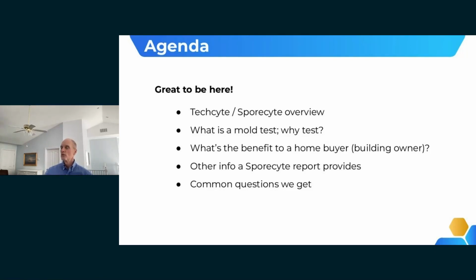You might look at it and ask, is there a moisture issue causing that? Is it a water leak, a roof leak, a window leak, or high humidity? If you could feel good about how to mitigate that, that might take care of it. Some people want to know specifically whether it is mold or not. So the surface test is great. If you're seeing something, perform that surface test and then you'll know exactly what you've got. But that will be up to you and how you want to approach it.